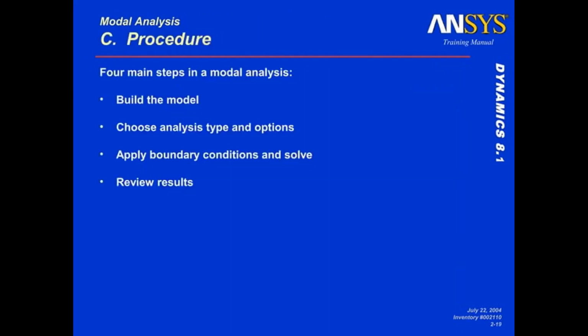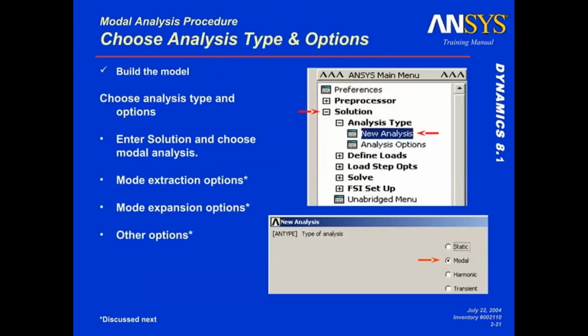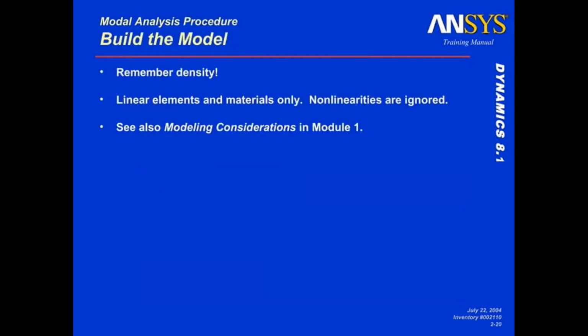The procedure for modal analysis: build the model, choose the analysis type and options, apply the boundary conditions, and solve and review the results. Building the model: remember, density is required, and linear elements and materials only. Nonlinearities are ignored. See the modeling considerations.